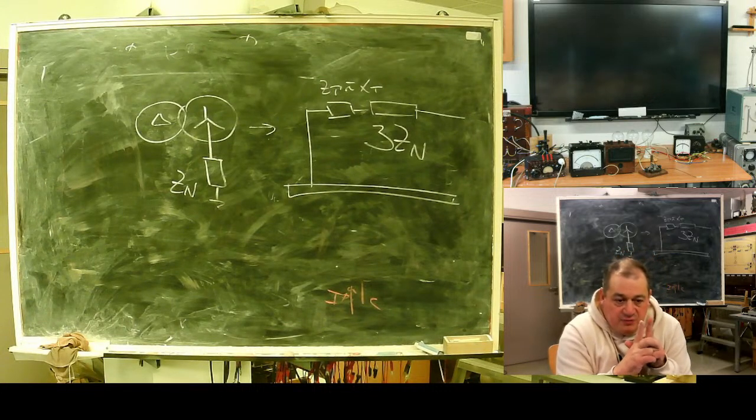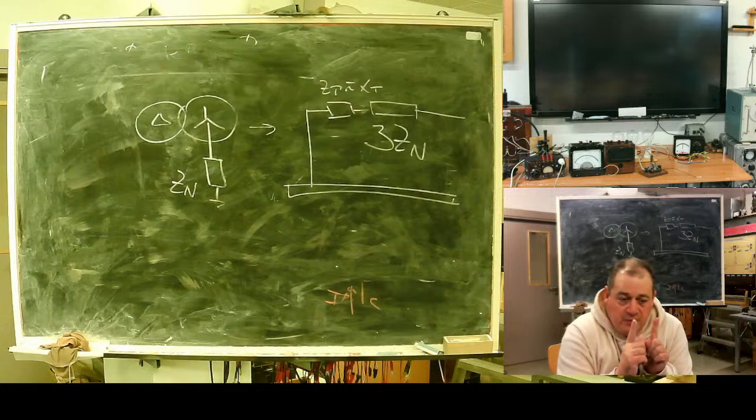Remember, in the method of symmetrical components, the influence between parallel lines for direct and negative sequence in most cases can be neglected. But for zero sequence, this mutual effect is significant. Between parallel lines, of all magnetic couplings, you need only one, the zero sequence magnetic coupling. This coupling is significant.